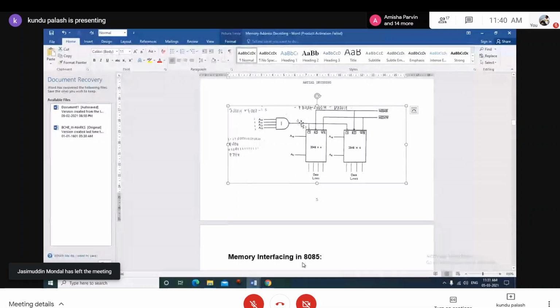So when the chip select is selected, according to the input output truth table condition, that means when all the signals over A13 to A15 are high, then it will be selected. So we can write the most significant lines all 111, and we assume the rest of the address lines all 0 and then all high. So the range of address for this diagram is F000 to F7FF.